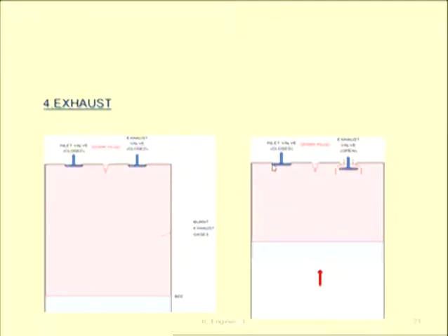So you can say that in an IC engine, a 4-stroke engine, out of 4 strokes, only one is a power stroke. Suction, we have to give power. Compression, we have to give power. Expansion or power stroke, we are getting power from this, and exhaust, again we have to give power. So if during 4 strokes only 1 is a power stroke and the remaining 3 are power-consuming strokes, how to manage this energy?